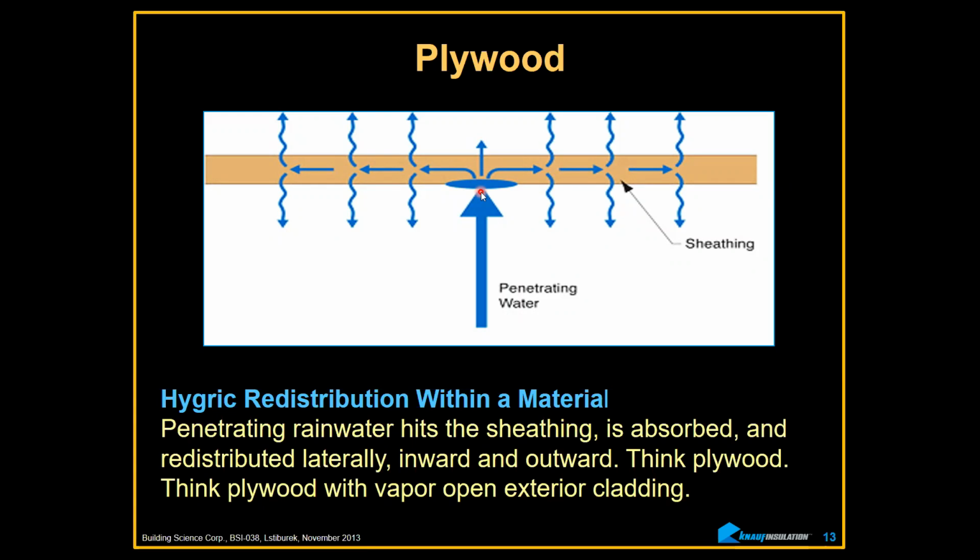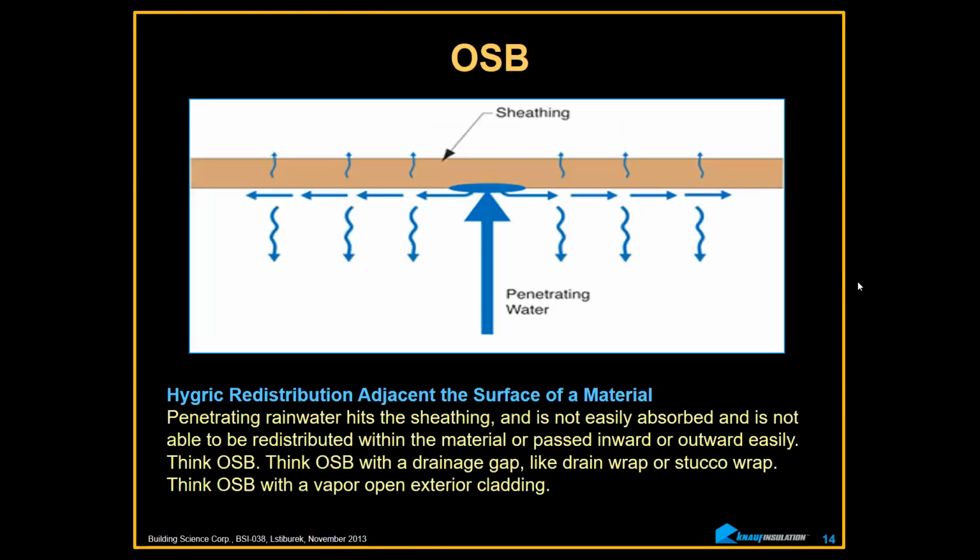Actually, the peeled lumber is the only thing that's on the face. And then we have layers all across, these linear layers. So the water is able to get in and redistribute itself laterally, and then it has not quite equal, but pretty close, the opportunity of releasing moisture in both directions, interior and exterior. So this would be the exterior, let's say in a rain condition, and this would be your interior. We want drying in both spaces. OSB is a different animal completely.